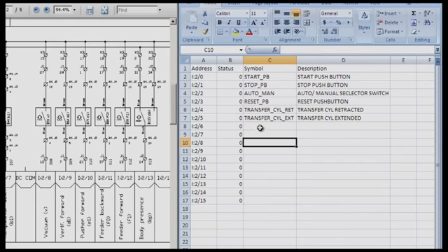So without doing all of these, what you do is you continue on in your programming. You keep labeling each one of these addresses. All of your inputs must have a unique symbol, and then you can give them a description as to what they mean to you. So for the last one on here, I'm going to use I:213, which is the body presence according to the manufacturer's schematics. And I'm going to keep that one because that one makes sense to me.